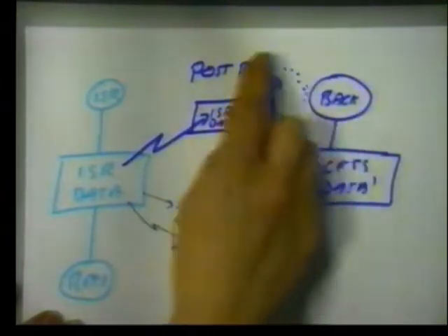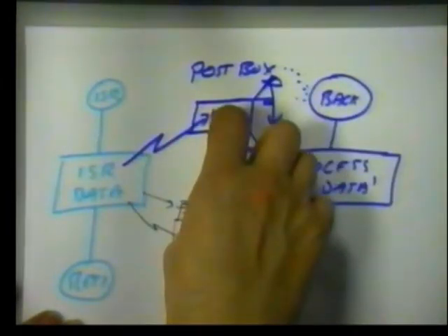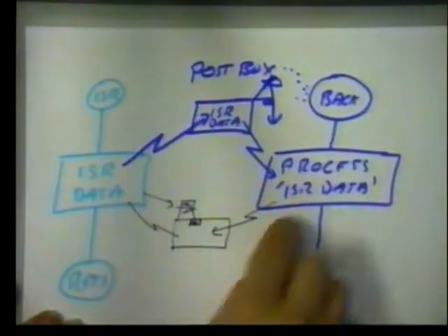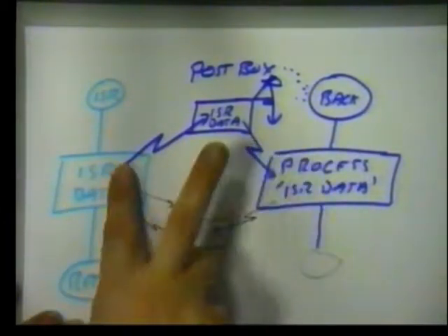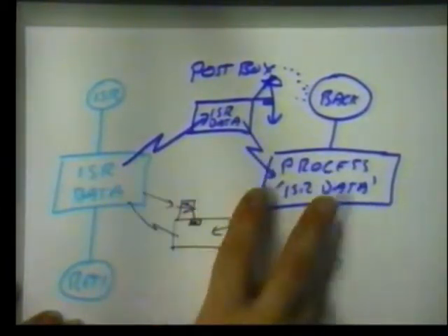So you need to set up postbox structures, semaphores and data areas to pass parameters backwards and forwards between the parallel processes. So, interrupt routines, very fast, very efficient, but complex data structures. Polling, much slower, very inefficient in processing time, but very simple data structures. That is the main lesson of that section.